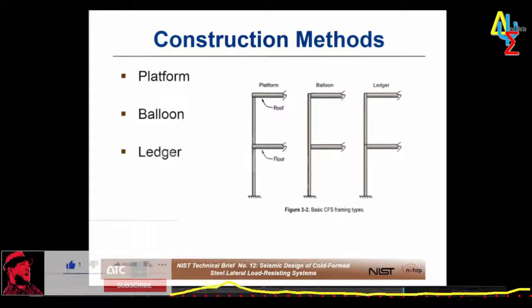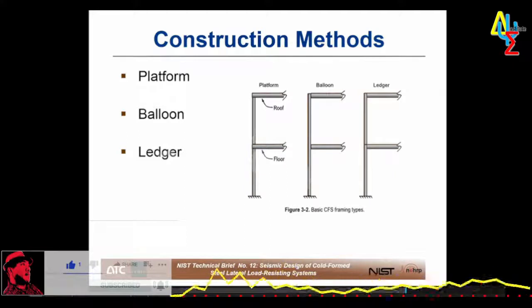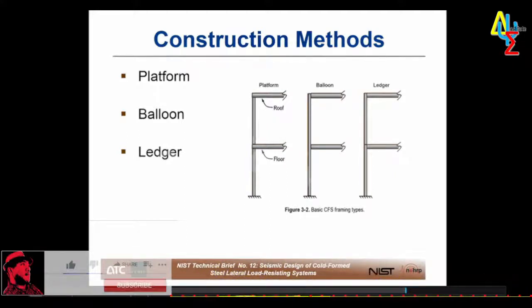And of course, framing can be panelized or framed in place, and panelizing does offer efficiencies for repetitive subassemblies, as well as some potential quality control advantages. However, panelizing does require considerable pre-construction time to design the panels, and in addition, interfaces with other constructions, for example, concrete foundations, can be challenging due to construction tolerances in these other materials.